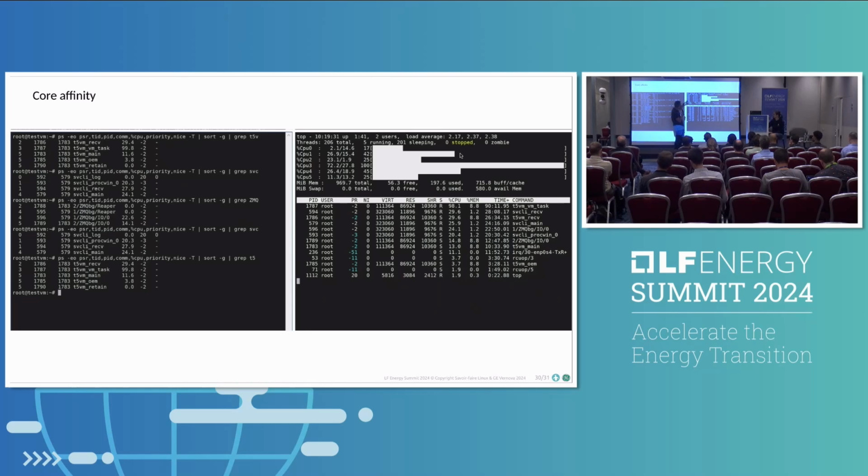And that is a graphic of how the load in the CPUs is distributed. You see CPU number 3 is reaching 100%. The reason is that CPU number 3 is in charge of executing all the protection algorithms. That CPU is 100% dedicated to monitoring if everything is going well when getting data from the power.